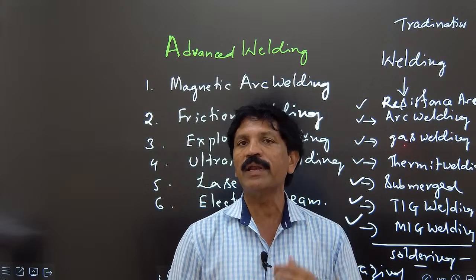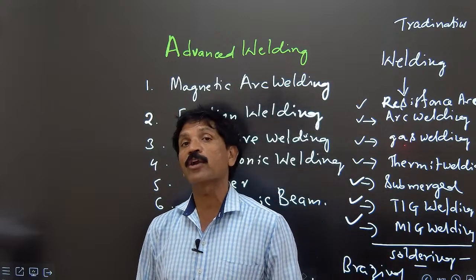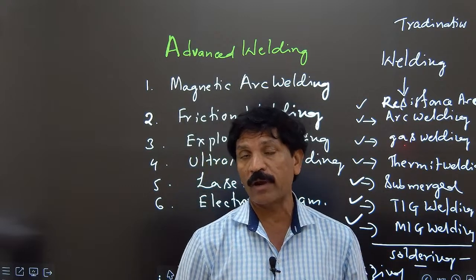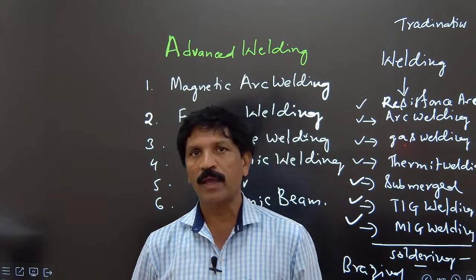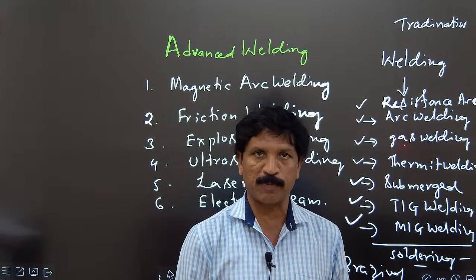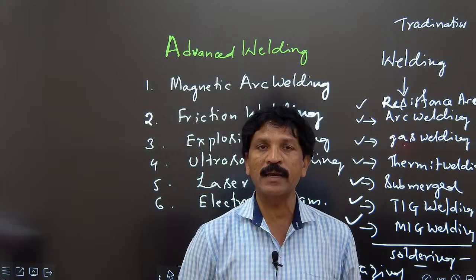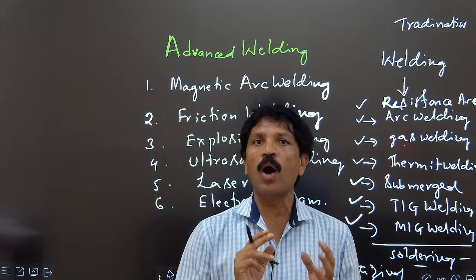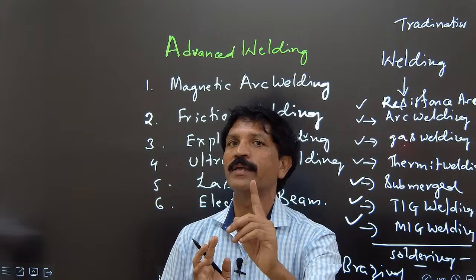In traditional welding, there are many defects. Defects means, if the electrode material is not proper, the weld bead will not get higher strength. Some other defects we can expect are porous holes, bubbles forming inside, and welding cracks. All these are defects observed in ordinary traditional welding.